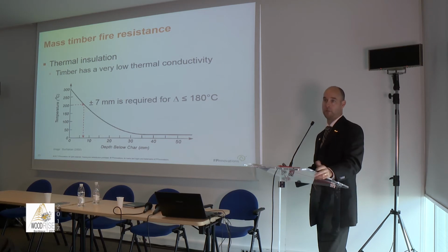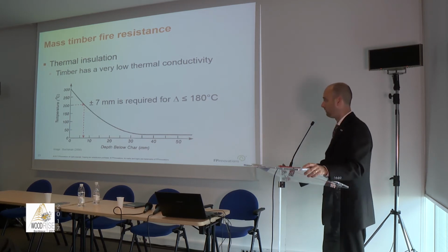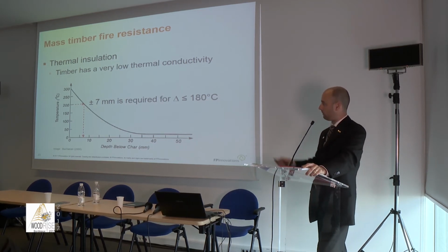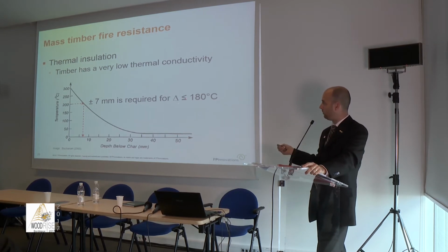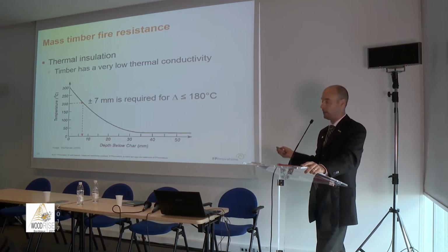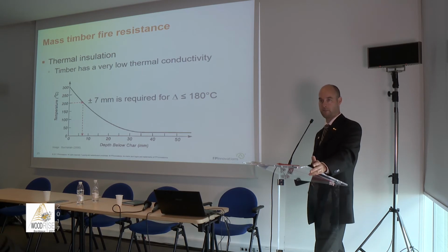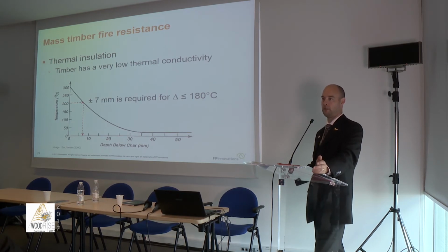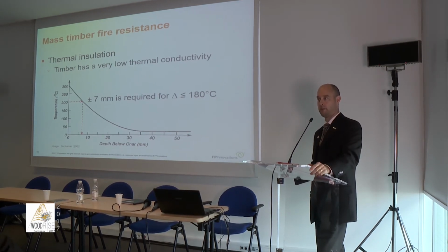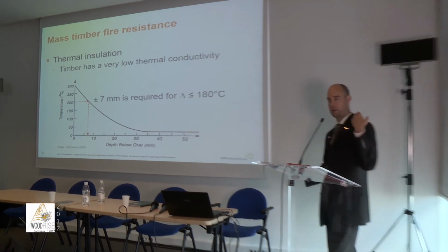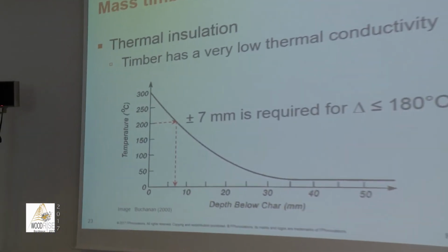Wood has a really low thermal conductivity value. So from the graph I've showed previously, essentially to meet the 180-degree rise criteria, we only need basically around 7 millimeter of wood if you have a fire on the other side. So it's really efficient.